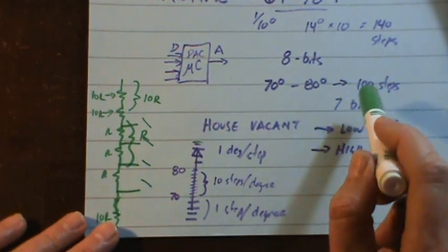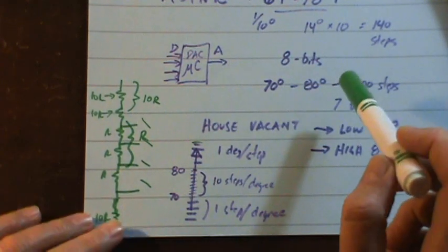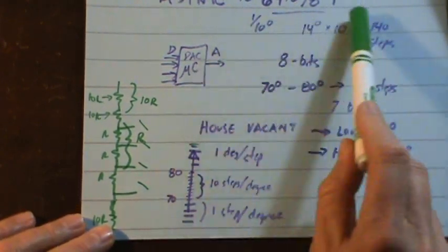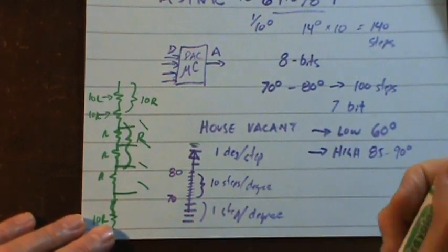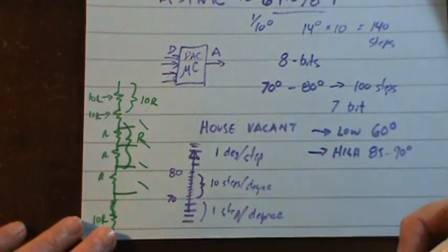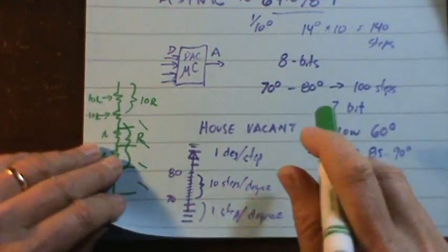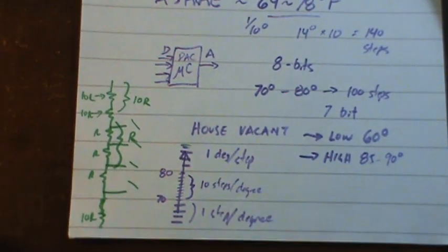As long as you've got something reasonable, the 7 to 80, you're kind of missing a little bit. I didn't take too much off, but if you covered a range of 20 degrees or so, 7 bits, 8 bits, if you went too far, I mean, you could assume, well, let's cover the entire range, and you might want a 10-bit controller. That gets a bit excessive. You're paying a little bit more than you need to there for that D to A.